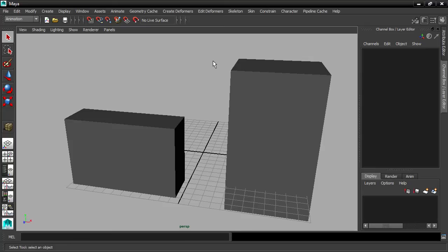But a lot of times in Maya, you have to build at a 1/10th scale, or even a 1/100th scale, especially if you're using dynamics, as physics engines kind of force you to use a 1/100th scale. So instead of building your character to be 170 centimeters tall, you build them to be 1.7 centimeters tall, a tiny itty-bitty little scale model. And this is common standard practice in Maya. So just be aware there's a whole host of headaches that come up with scale in Maya.